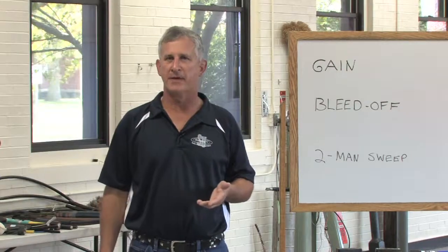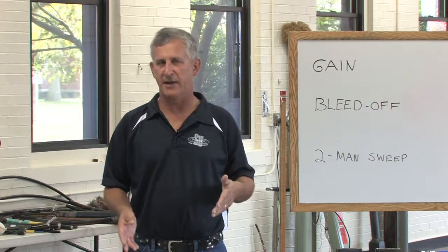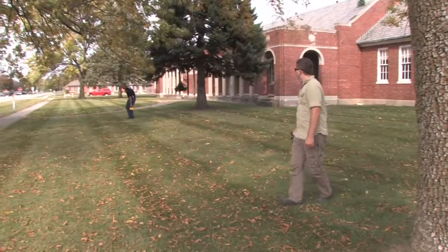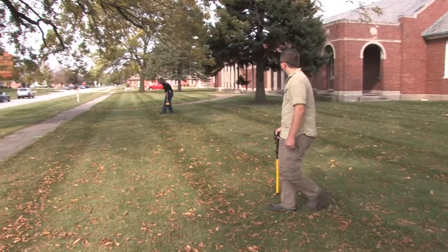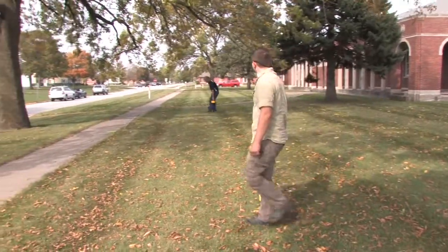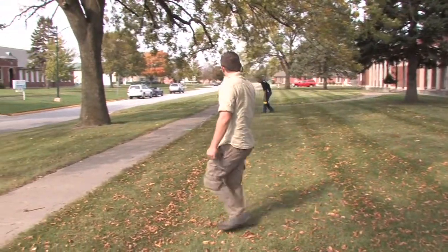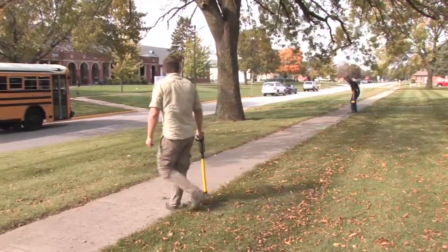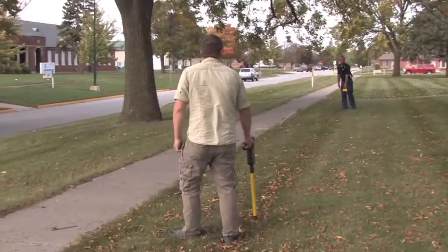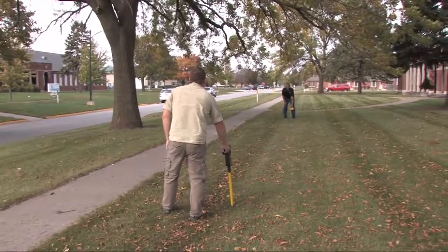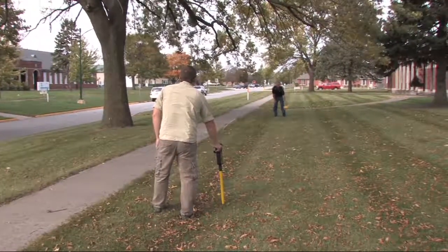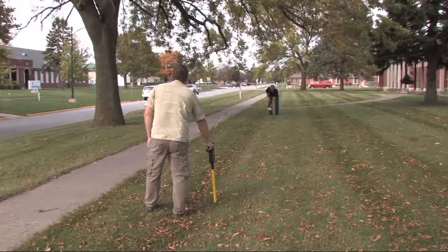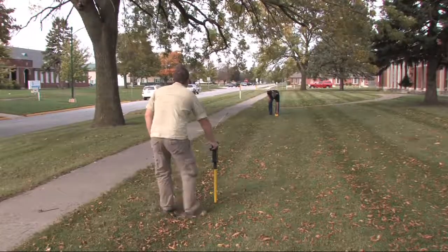The purpose of a two-man sweep is to inductively locate one or multiple buried targets. Two lines are detected during this two-man sweep. The purpose of the two-man sweep is to place the transmitter directly above any line found during the sweep. Once the transmitter is atop the line, the locate continues in normal fashion with the receiver.